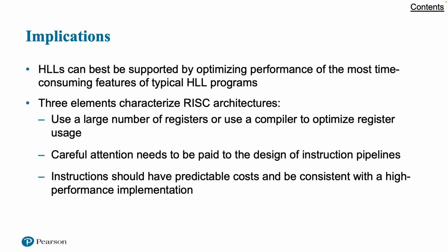Second, careful attention needs to be paid to the design of instruction pipelines. Because of the high proportion of conditional branch and procedure call instructions, a straightforward instruction pipeline will be inefficient. This manifests itself as a high proportion of instructions that are prefetched but never executed.